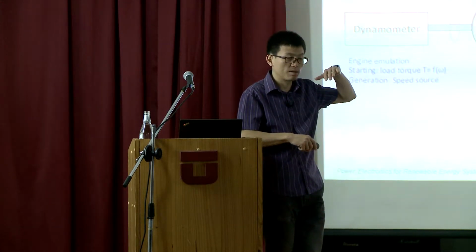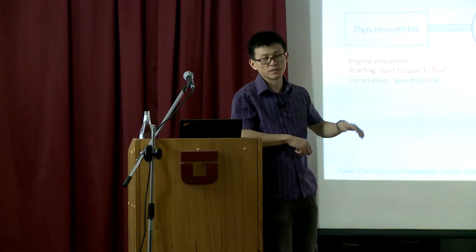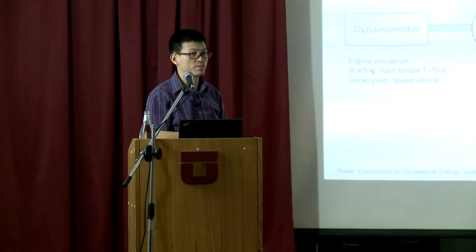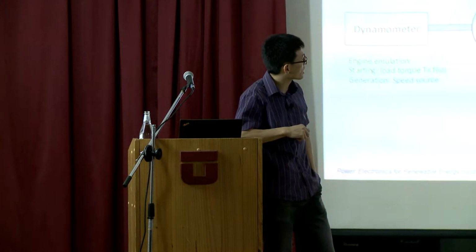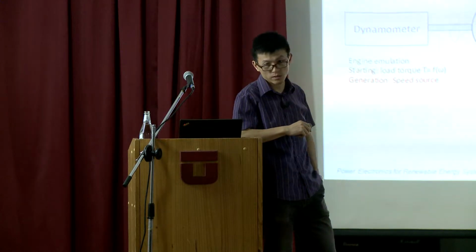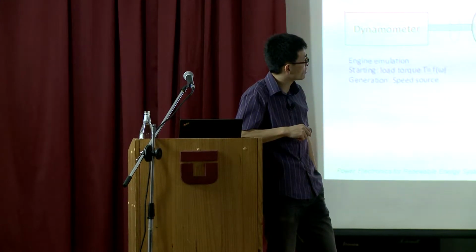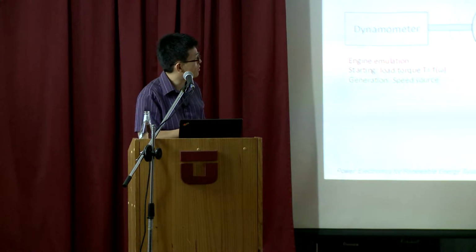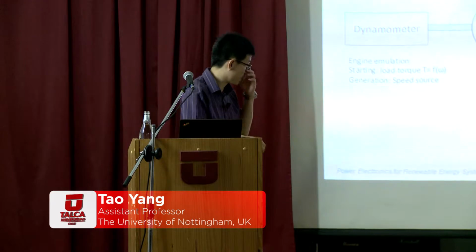In that case, the current supplied here, the IDC current, will follow the droop concept. If the voltage is 270 volts, there will be no current. If the voltage is below VO, 270, the current will flow to the load. But if the voltage is higher than 270 volts, it means regeneration: the power flows from the GSS to the generation system, and the current will flow into the power converter. This is the concept we use in the droop.